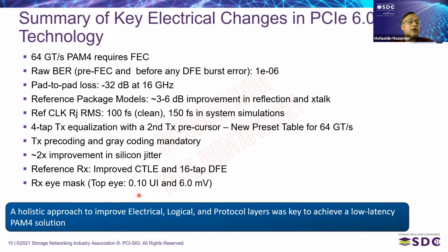Overall, by making all these improvements in the electrical layer, logical layer, and protocol layer, we are able to achieve a low latency solution that still has better power efficiency than PCIe 5.0, and supports PCIe 5.0-like channel reach.